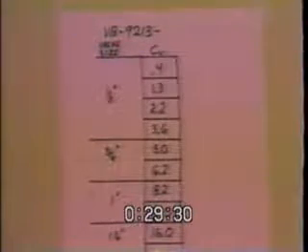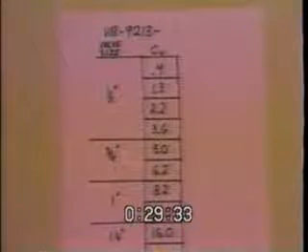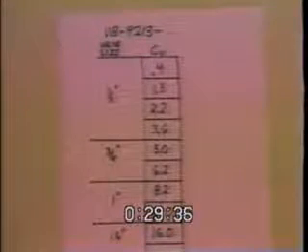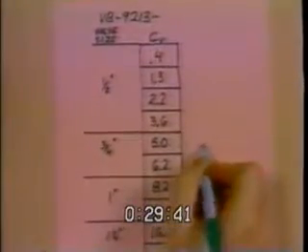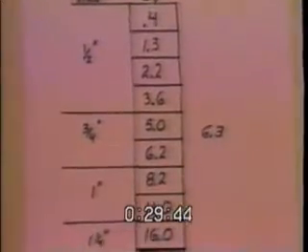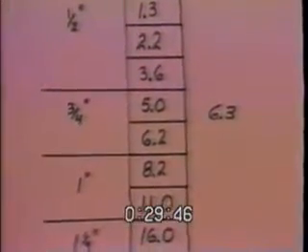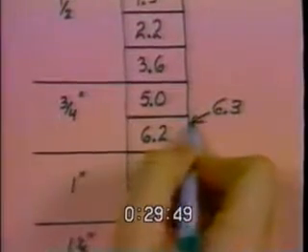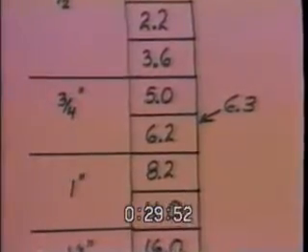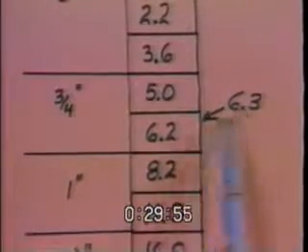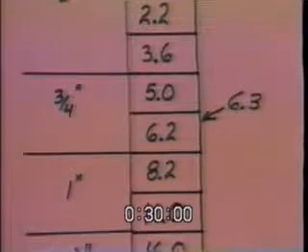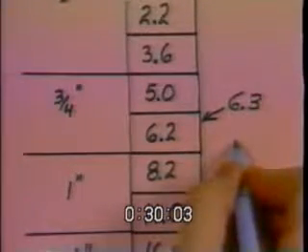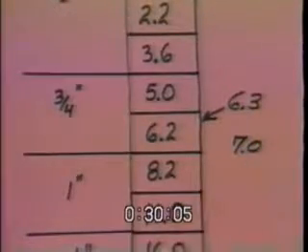Once you've determined a CV for either the steam or the water valve, you need to go to the valves to find out how close you can come, finding an actual CV. The other was a calculated CV. In our examples for the steam valve, we had a calculation of 6.3. It's very obvious then that you take the one closest to that. In that case, 6.2. So our calculated CV would be 6.3, but the actual CV would be 6.2 because that's what the valve has. In the water system, it's a little difficult because we had a CV of 7.0.